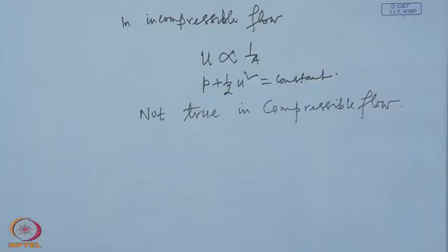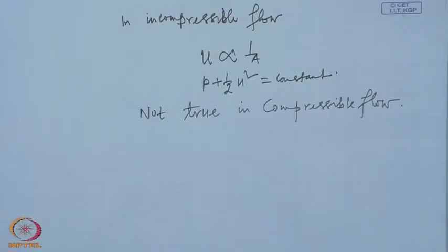Now, of course, all these equations can be obtained from the general mass conservation, momentum conservation or energy conservation laws that are derived in basic courses in fluid mechanics. However, in this case we will derive those equations from first principles once again, applicable for one dimensional flow.